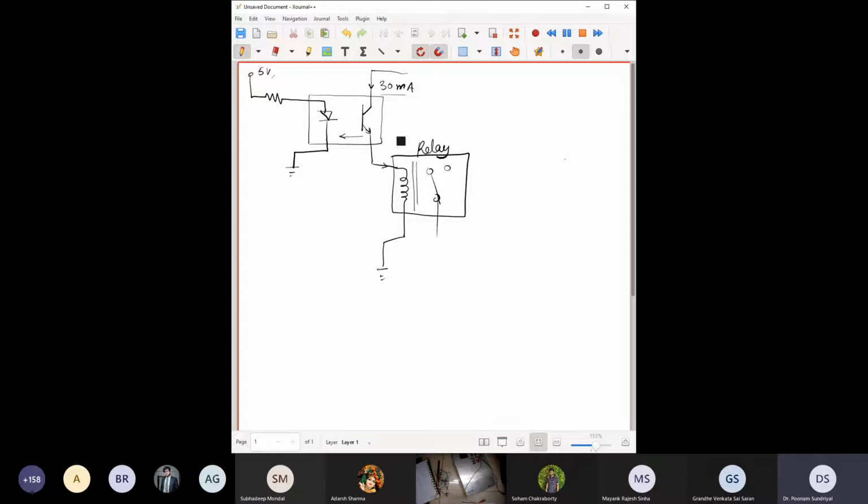Okay, this can be a typical circuit. Say this relay is a very heavy duty relay, and it requires maybe 100 milliamperes to stay on, so the holding current under question is 100 milliamperes. Say it's a relay for a big CNC lathe, maybe for a CNC spindle. This could very well be the holding current.